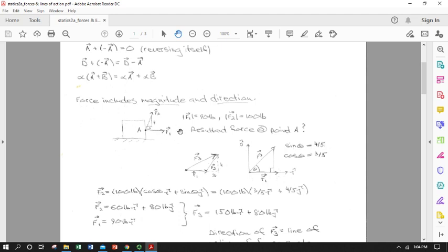And then the next orthogonal direction, F1 is in the x direction, the y direction would be pointing straight up. If we got a vector that had a component that was the same as F1 plus F2 in the x and the same as F1 and F2 in the y, we would have its equivalent. So what we want is an F3 that is F1 plus F2.